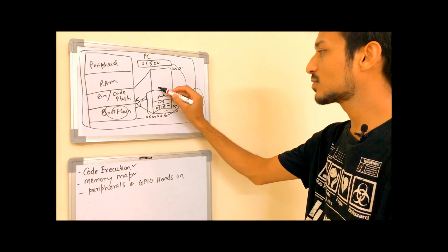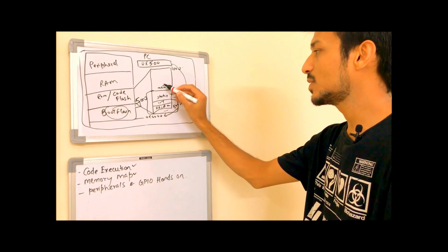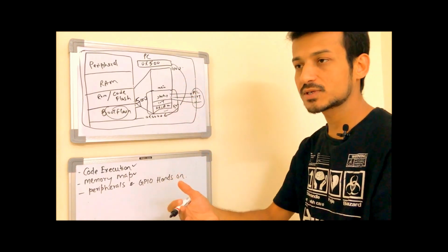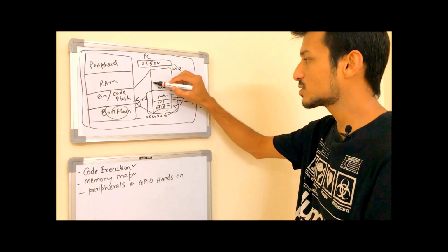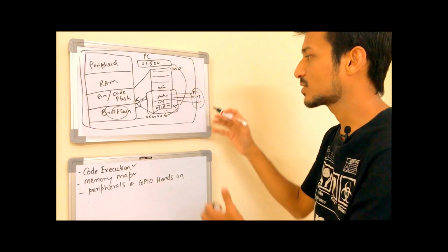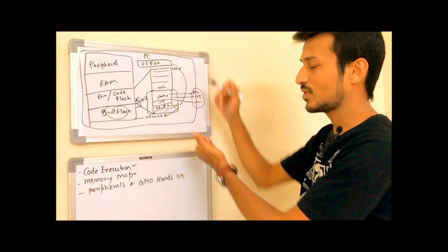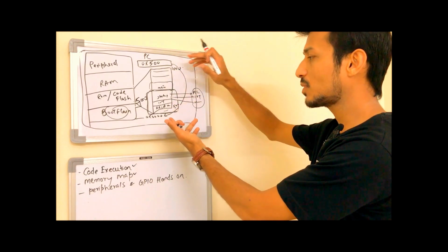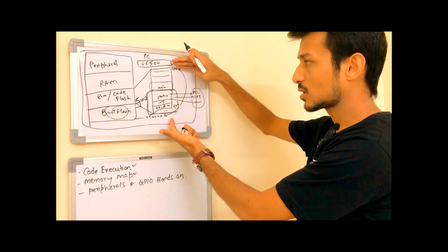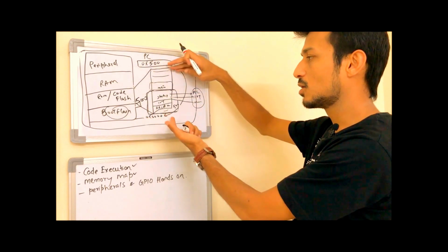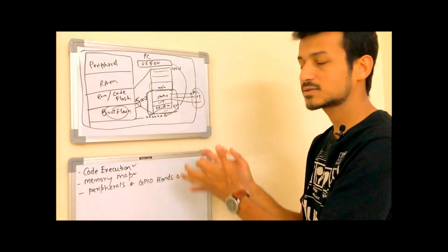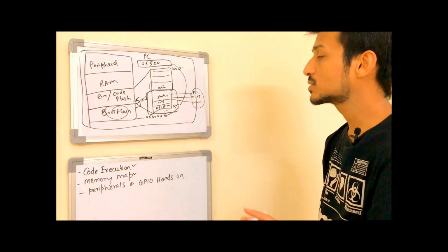After the startup code, your main code will be here, your main function, and if you have any other functions in your code, all the functions will have some memory space in this code flash only. This is not the function stack I'm talking about. This is the code area, the text area, which has the low level binary instructions, the opcodes.